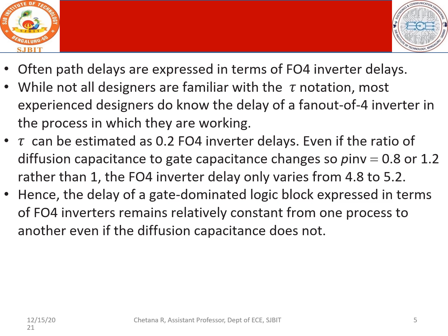Gate dominated means the input is given at the gate. The delay in terms of FO4 inverters will always be relatively constant from one process to another, even if the diffusion capacitances are not. So it always normally remains constant.